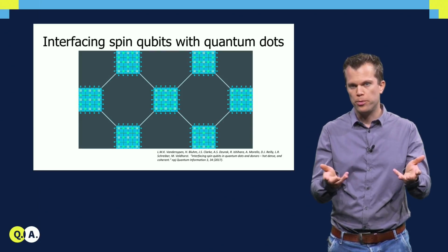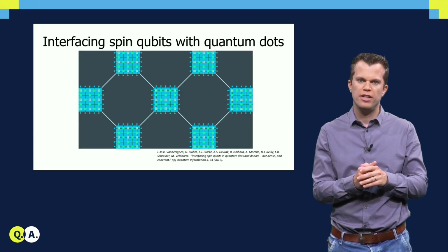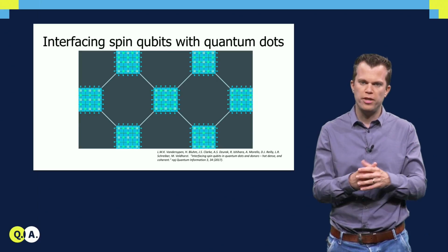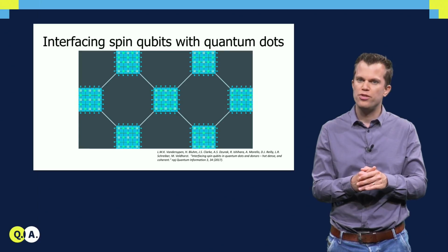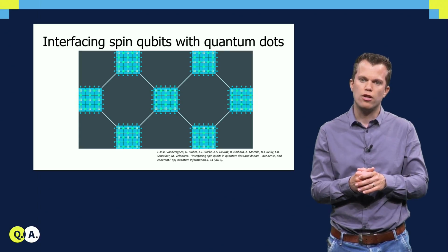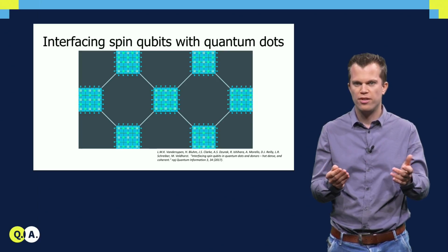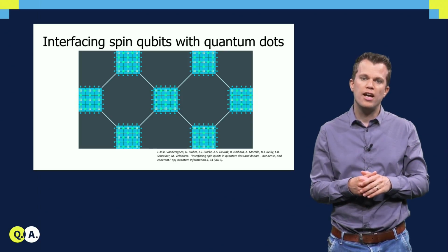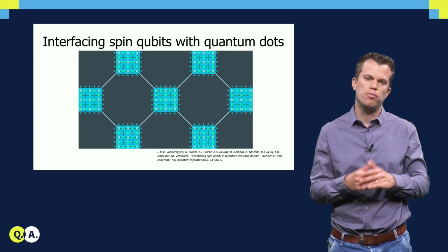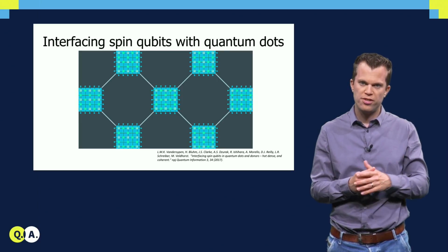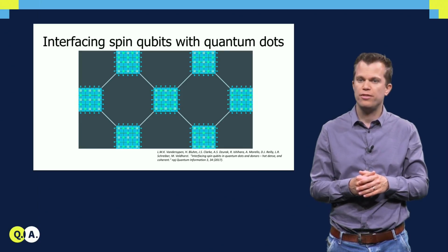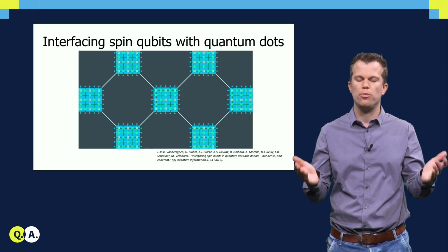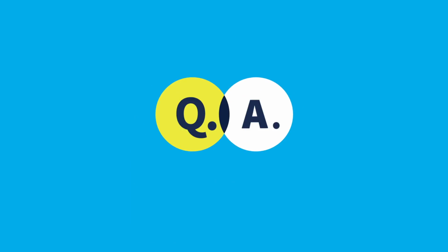In the field of quantum dot quantum computation, the vision of a future quantum computer is one where small arrays of quantum dots are coupled together using long-range qubit links. The small arrays operate using the ingredients as we discussed here. The long-range links could be based on quantum buses, where an electron spin is transported over an array of quantum dots. Alternatively, the electron spin can be coupled to photons in superconducting microwave cavities. Such approaches are now actively being pursued, and rapid advancements are being made. And these lay the foundation for a future quantum dot quantum computer.